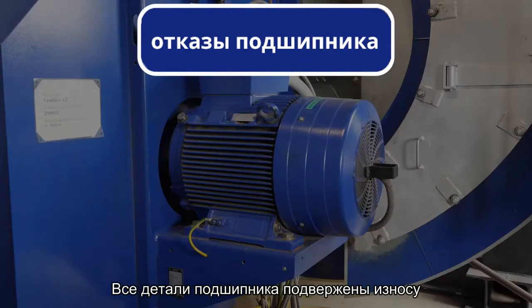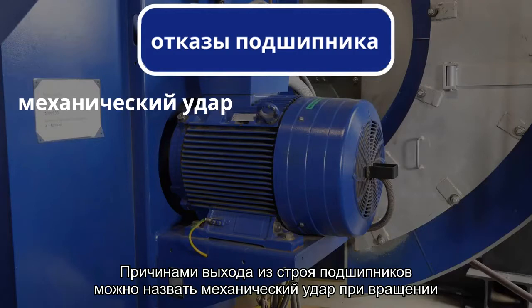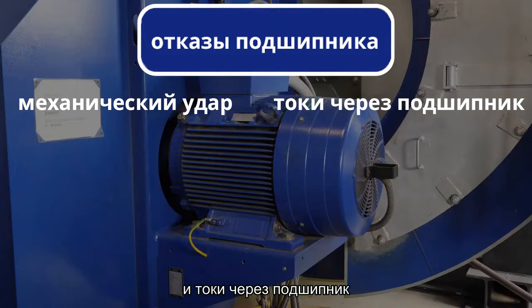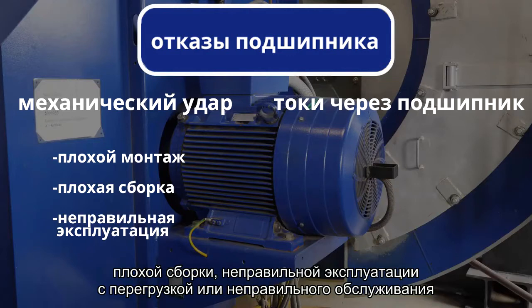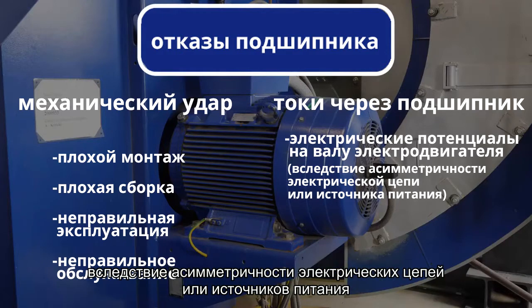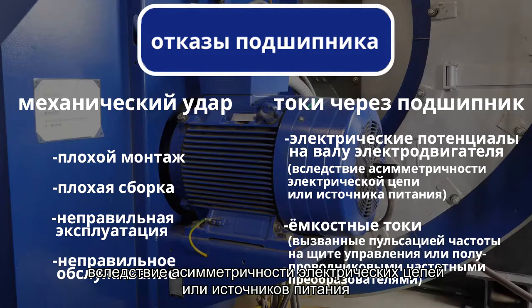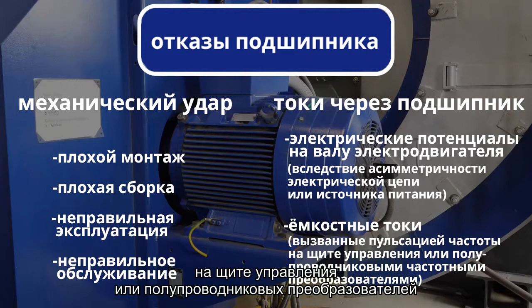All parts of the bearing are subject to degradation. The cause of bearing failures can be considered as mechanical stress during rotational movement and bearing currents. Mechanical stress can be caused by poor installation, poor assembling, or by improper use, overloading, and poor maintenance. The bearing currents can be caused by shaft voltages due to asymmetric electrical circuits or power supplies, and capacitive currents caused by the pulse frequency from the power supply control of semiconductor converters.